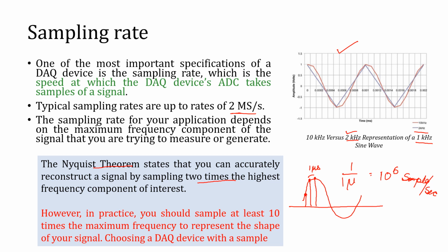And when we take 10 kilohertz, it tries to convert into a somewhat sine wave. Although it is not exactly a sine wave, it gives us a bit more real information that the signal is not a triangular wave. If we increase more, let's say to about 40 kilohertz, maybe our sine wave becomes smoother at the edges.